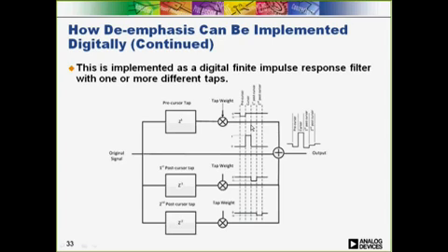In the first postcursor time period, which is right here, we add a signal with -1/2 as the tap weight. So basically it's inverted and half the amplitude of the original signal. And then in the second postcursor time period, we can see the tap weight again is -1/4. So all these signals are added together, and the resulting output is a pre-distorted waveform that looks something like this. So this is an example of a 3-tap case.